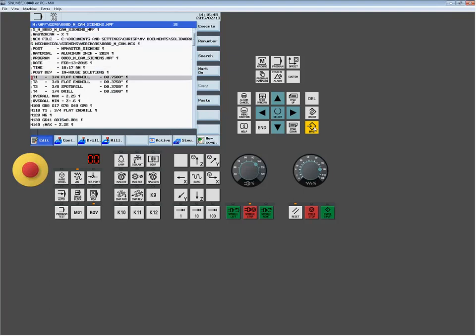So I have some tooling notes. I got a few different tools defined for me, as well as maybe posting time, source files, that kind of stuff. Then from there, anything below these semicolons, so all the semicolons are what we call comments. So anytime you want to put any type of user note in the program, just simply put a semicolon. Everything after it will be ignored.